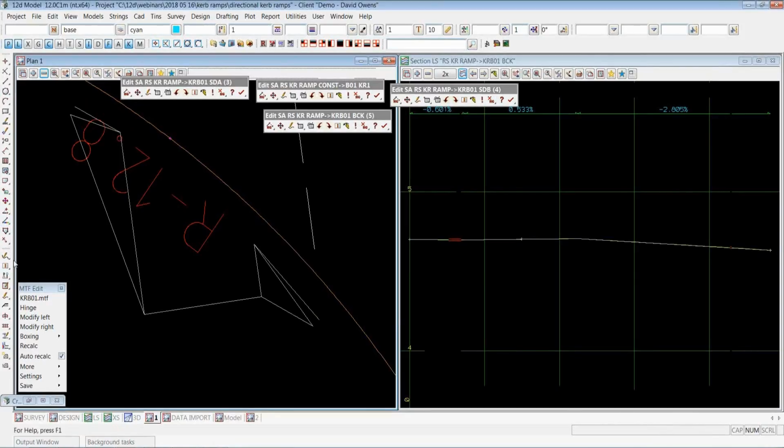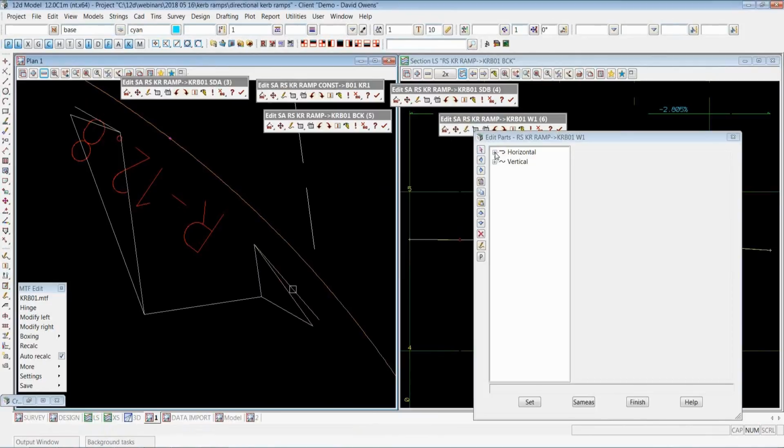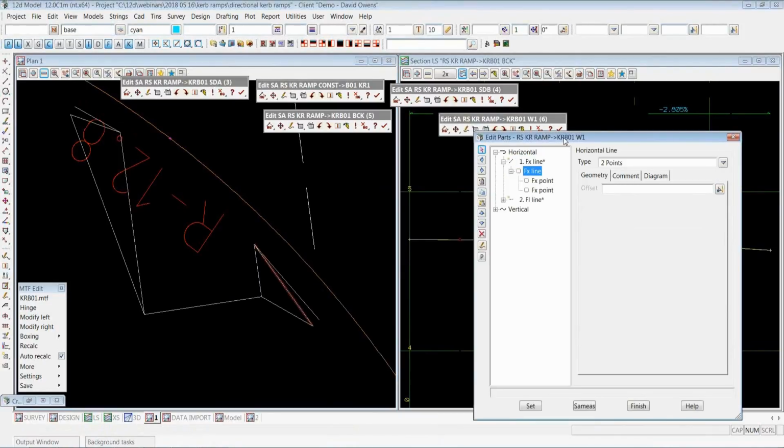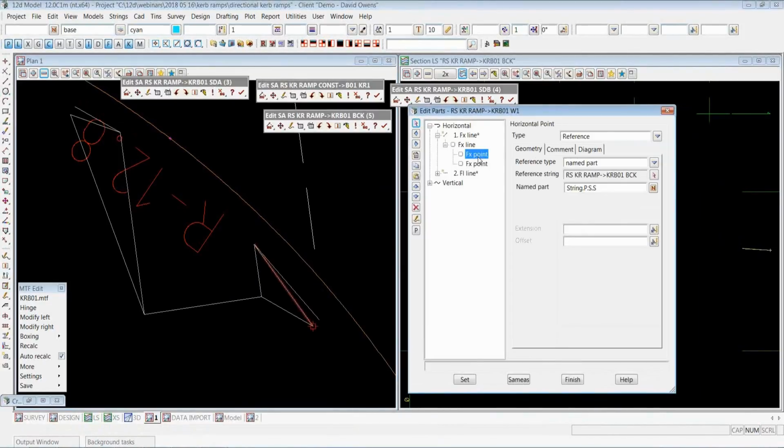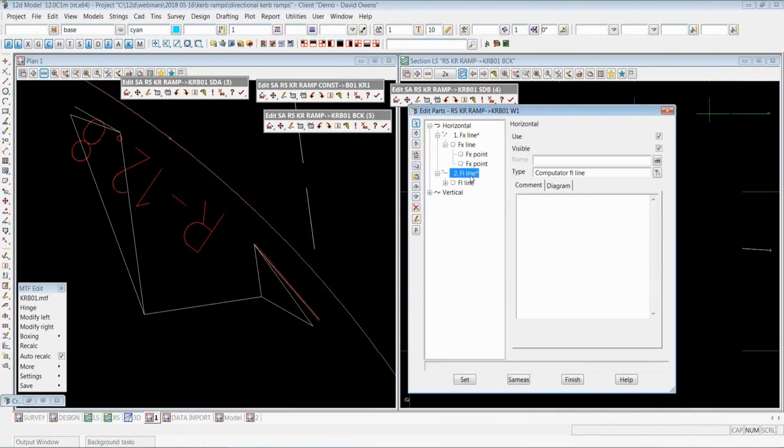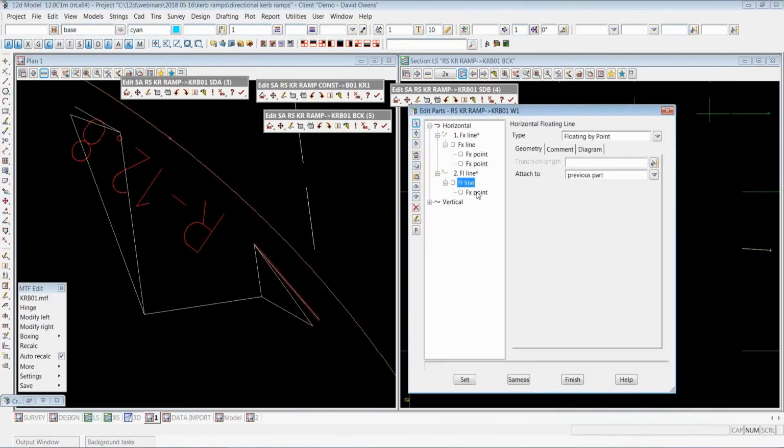So it goes from basically having no curb at all from this invert point, transitioning up to the full height and the full size of the curb. Again, nothing particularly outrageous about the string itself. It's once again simply joining dots. The first point is just the start of this little back string through to the start of my side string here.